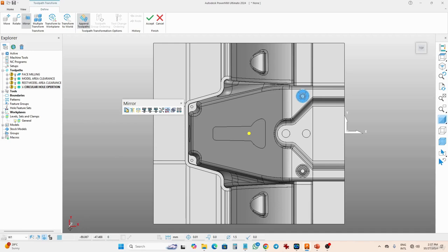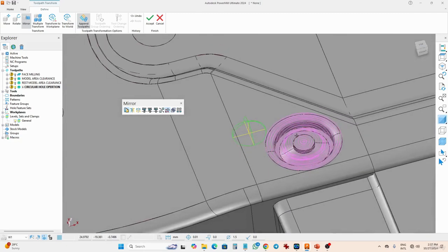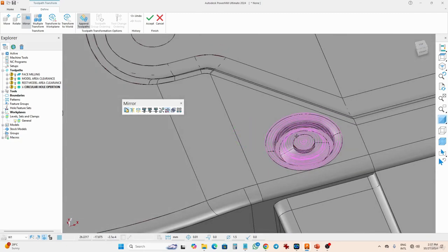And then the Y and Z axis, which is going to be this one in the Y direction. So we want to make the mirror about this position, so that is going to be the X and Z axis. If I click over here, you can see that it gives you a preview of where the operation is going to be performed. So just go and click OK.